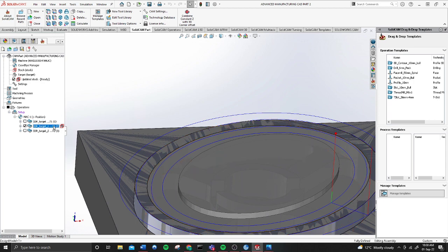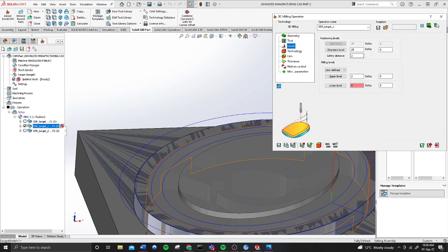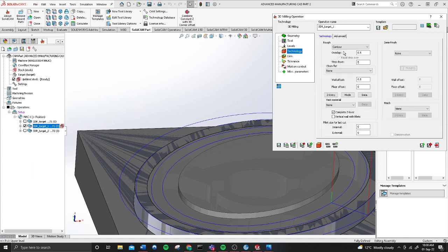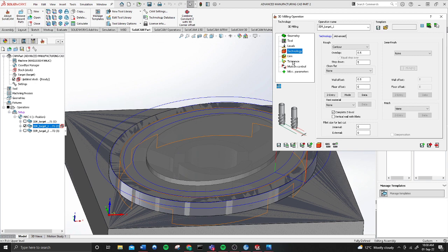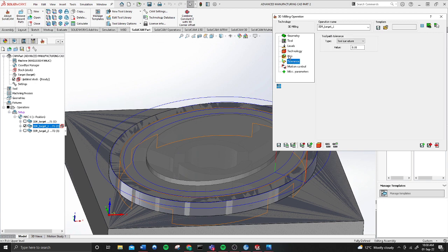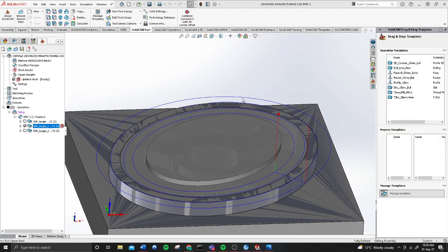So it's got, again, a 0 floor offset using the 10mm. So lower level here is set as this, and then the upper level set at the +2. On the stock technology, we're going to use a contour, pretty high step down, pretty average overlap, just because it's a very basic operation. And then the floor offset's going to be 0, so we're going to be right down at the part level in this pass.